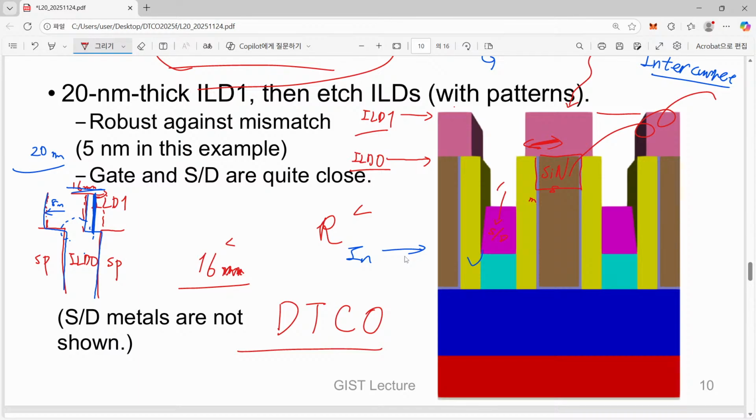So in that case, these kinds of relatively small ideas, changing something, especially in terms of the interconnect MOL layer, can introduce a lot of advantages, because previously people concentrated on FEOL, because that was the key part where performance was determined.